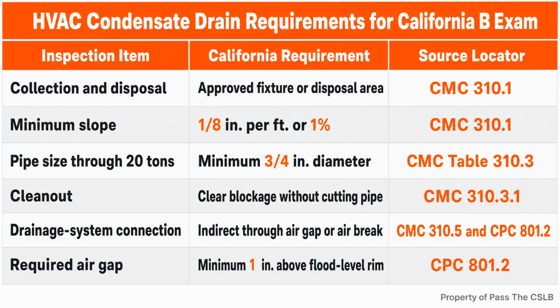The heating and air conditioning installer controls the condensate route, while the plumbing work provides the appropriate receptor and drainage conditions. The general building contractor has to make sure those two scopes meet correctly, instead of leaving each subcontractor to assume the other one finished the connection.